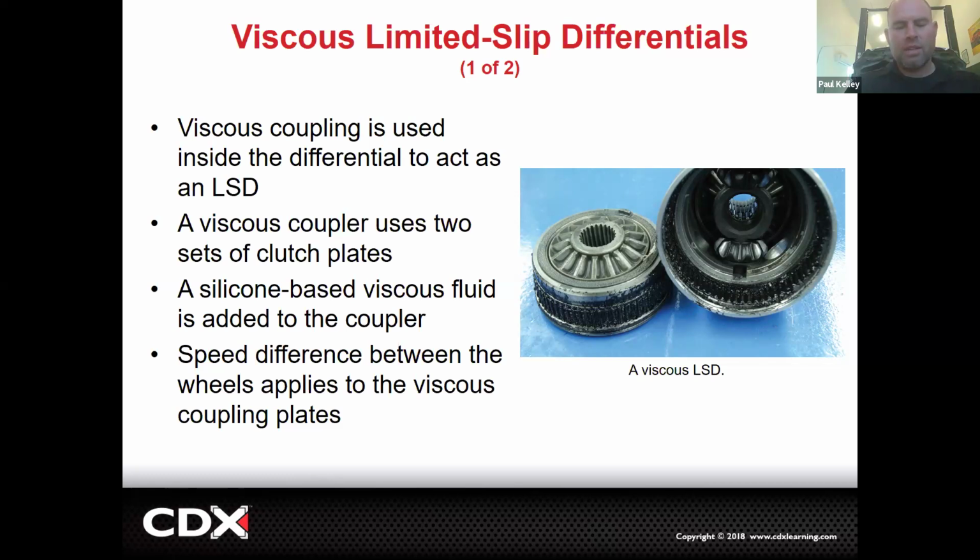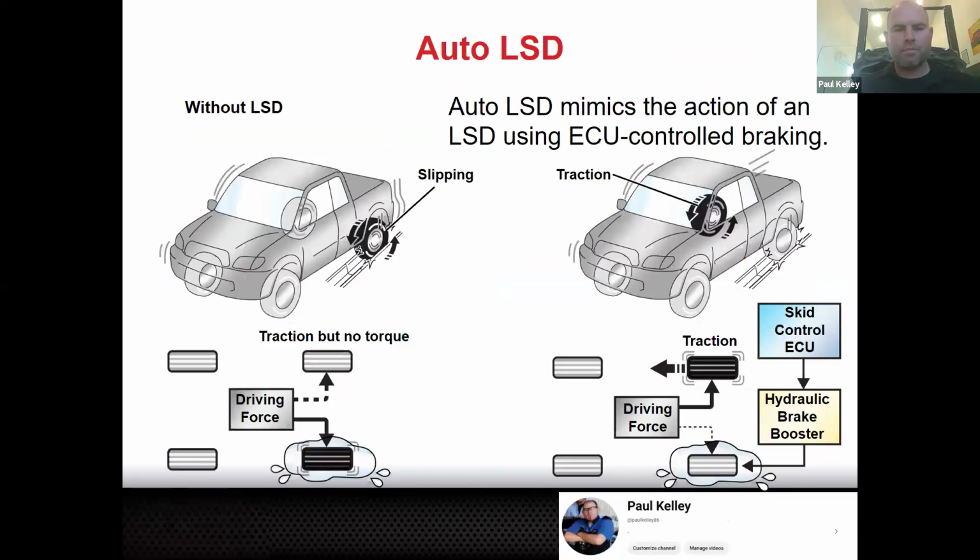Okay, so regardless, the way that the all-wheel drive works, it's not exactly a differential because there's no spider gear type of stuff always happening, but there's clutches, and the clutches allow it to slip, so that allows a speed differential. But then when there's too much slip, it pumps the clutches up, so that stops the speed differential. And that's why it's a differential, but barely. Cool, so that's kind of an interesting one. And then we got some computerized stuff.